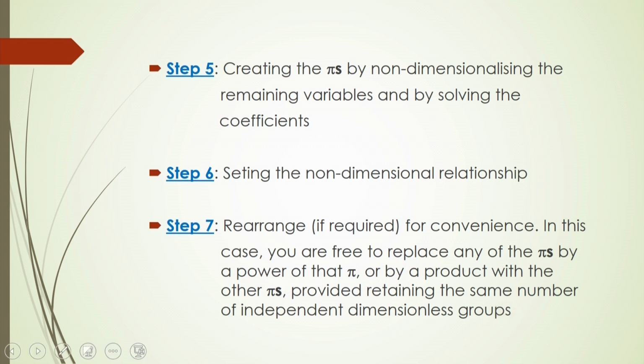Sometimes it is required to replace any of the phis by a power of that phi to get the significant dimensionless groups, or you can make these significant dimensionless groups for your convenience by a product with the other phis. Of course, whenever you are making these convenient dimensionless groups, you have to remember that the same number of independent dimensionless groups will remain in the system.